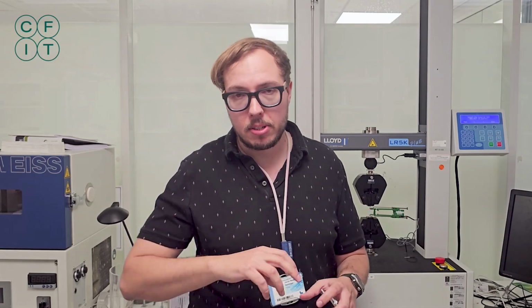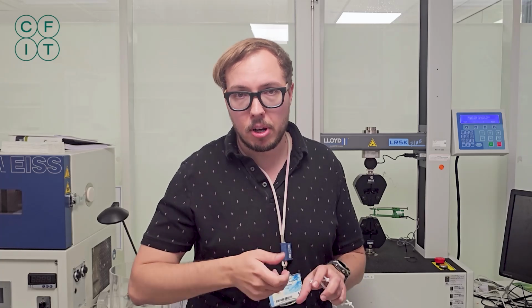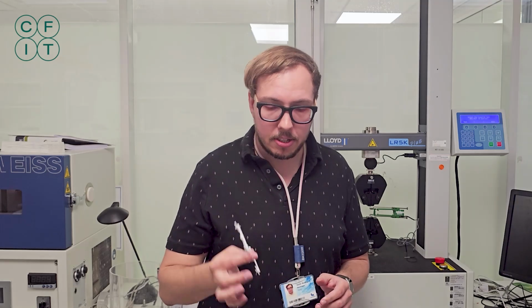It essentially has a function of locking up the device when there's no drug remaining, because the patient just can't keep dosing when there's no drug left. That is made of POM today, and this is the cold runner for it, but it's a little white ring. So 84% of the total shot volume in the injection molding cycle was being discarded, and only 16% was actual product. In the past, we ground that up and incinerated it because we believed, and it is true, that when you recycle POM, there is degradation happening of the monomer chains. That is a fact. But we challenged this some years back to say, okay, what if we actually characterize this?